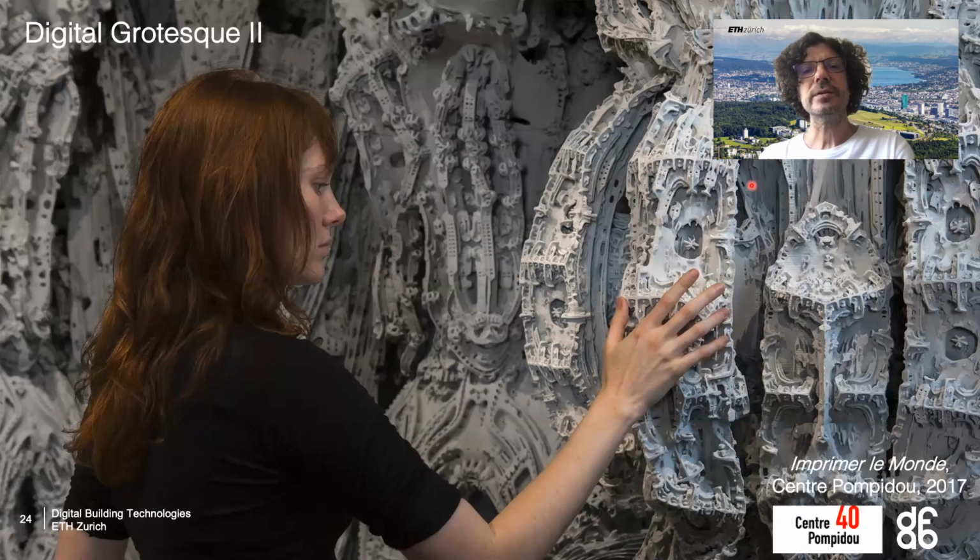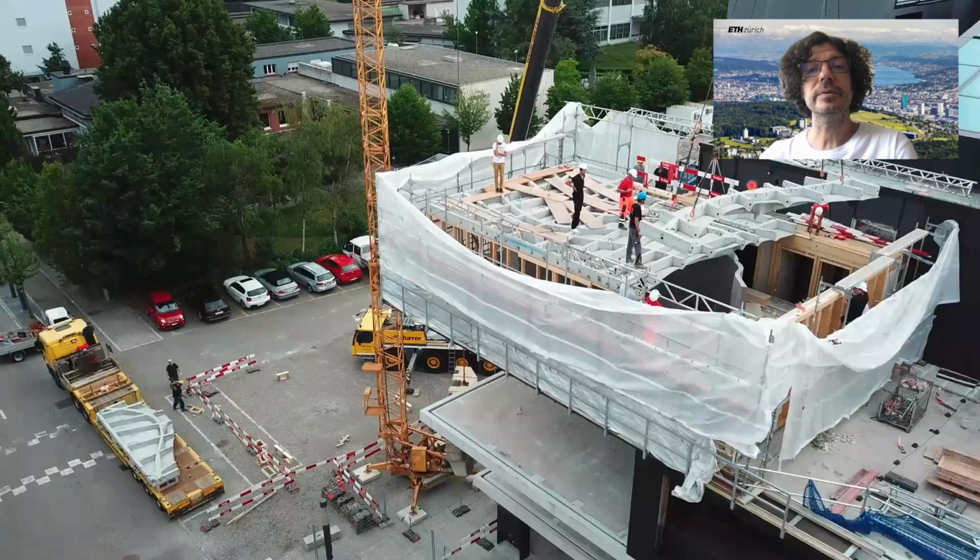Of course, the question is, why would you want this? Well, in fact, you can have aesthetic reasons, but there can also be objects that are more complex to realize because of overhangs, because of cavities, and all of those situations are ones where we could find an interest for digital fabrication with this process. An option is actually to use this sand bed printing to produce formwork for concrete. And an example of the resulting shapes is shown here.